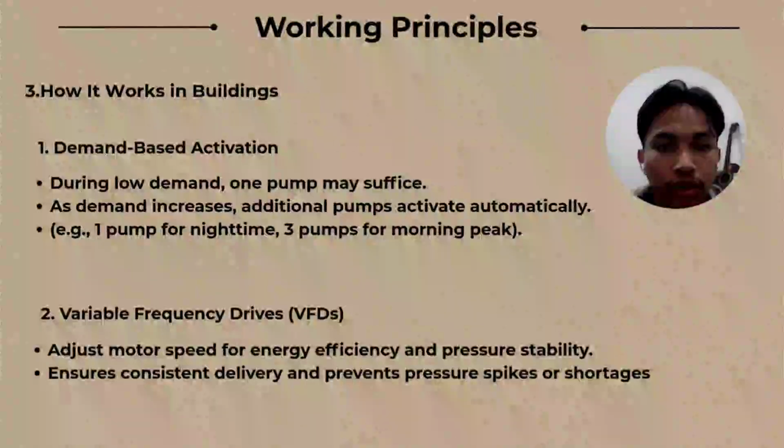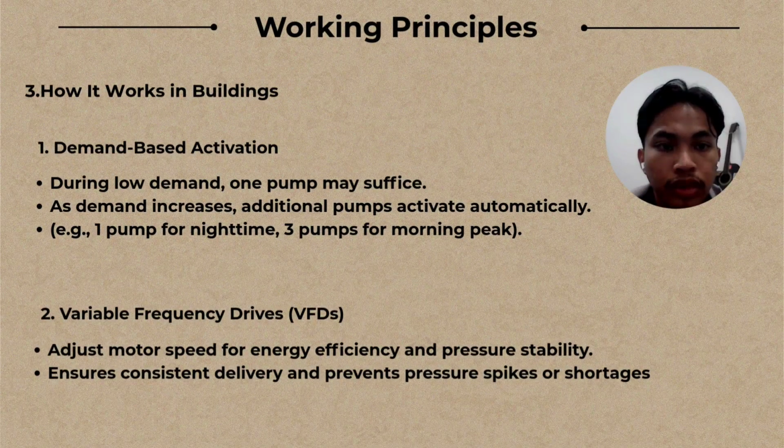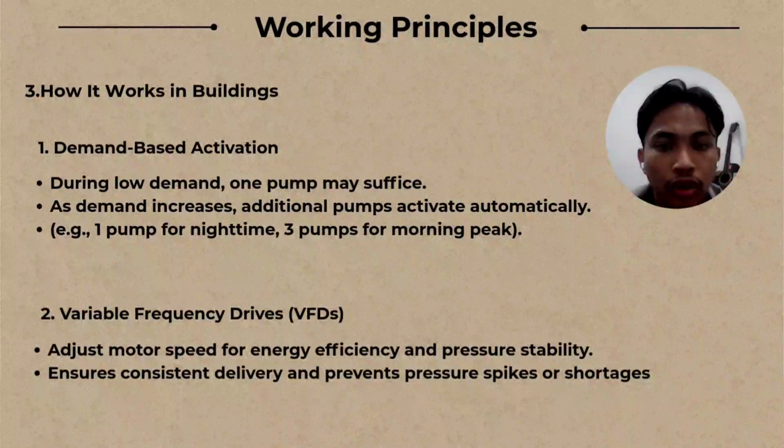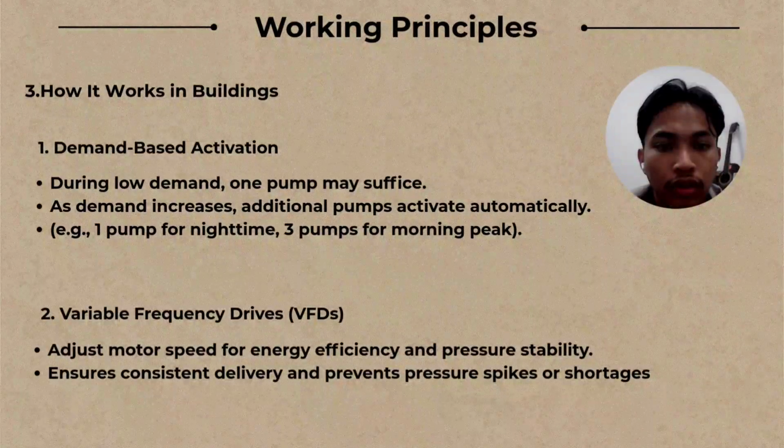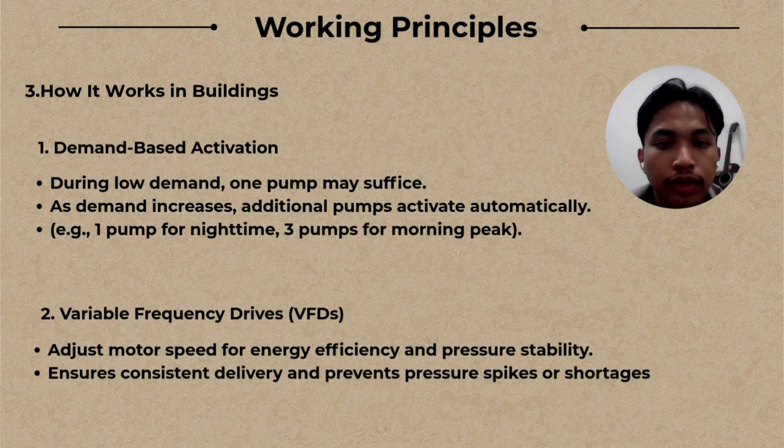So the second one is pump in series pressure boosting. Pumps in series are used when higher pressure is needed, such as in tall buildings. Water flows from one pump to the next, increasing pressure step by step to reach the upper floors effectively.